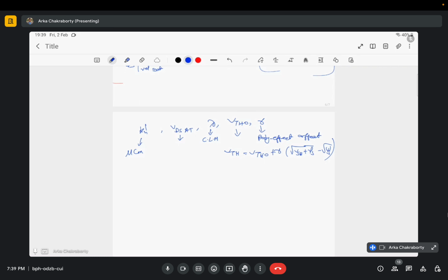There are lots of interesting phenomena that happen in MOSFET. Like we were saying that mobility of NMOS is twice the mobility of PMOS. But interestingly, when you go to low enough nodes like 7 nanometer or even 15 nanometer or 24 nanometer, something called stress effects come into the picture, and the mobility of NMOS and PMOS almost becomes equal. So you don't need to maintain WP equals twice WN, that you don't need to maintain.